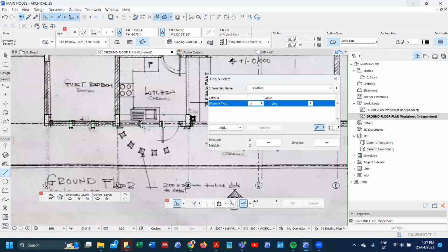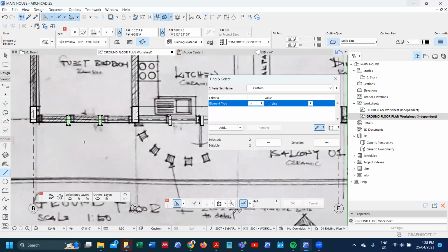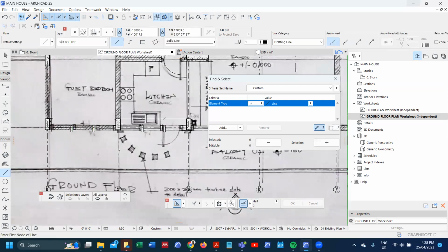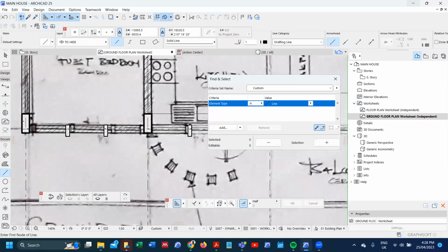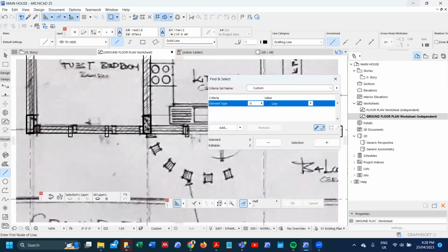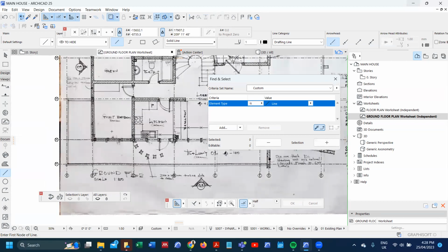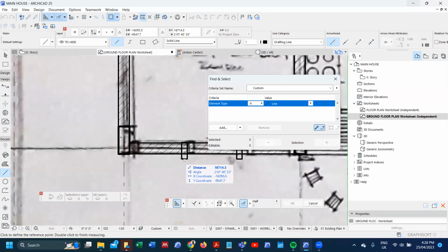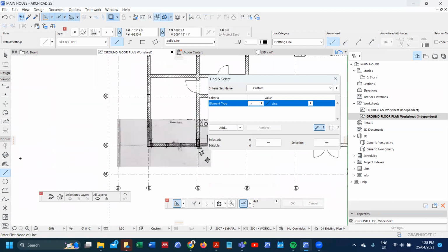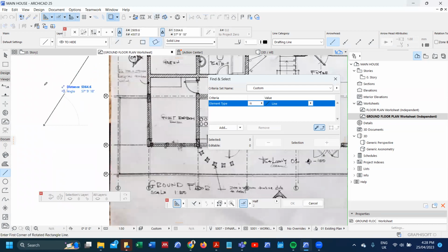Now, these are things that you can easily refine when you are drafting using this tool, as opposed to when you're drafting manually, because you can see there are 2 or 3 things that are getting lost on the drawing that we're trying to correct. So with that, we can comfortably now place our windows. Now, our windows is the same logic like our doors. We just need to understand them. Okay. In our case, we have a window from here to here, which is around 950. So let me work with a box of 950.